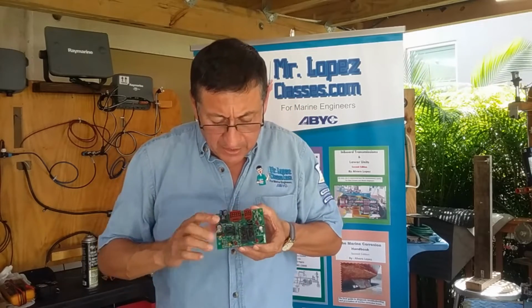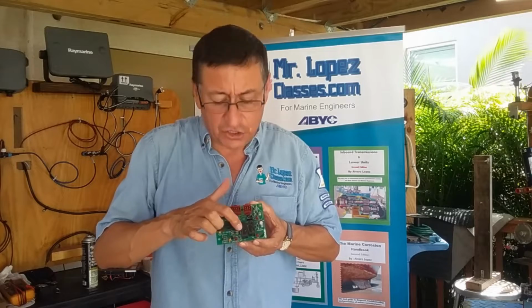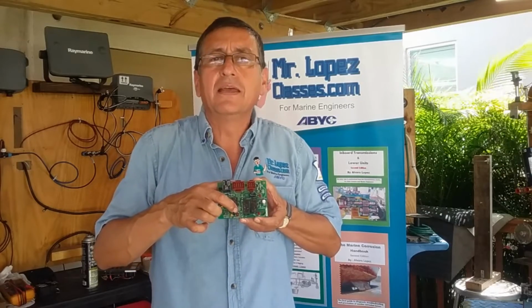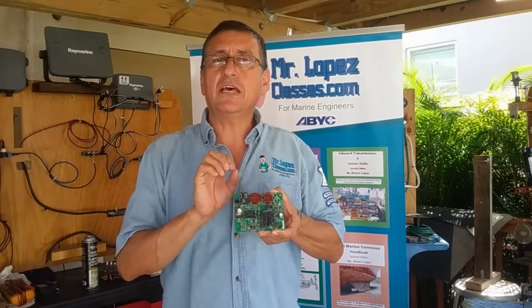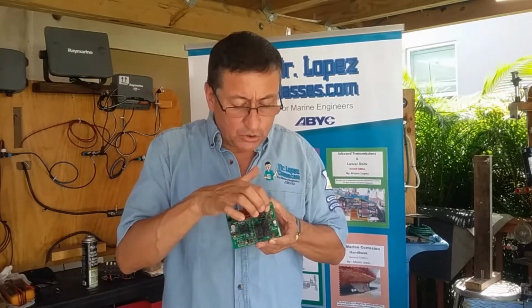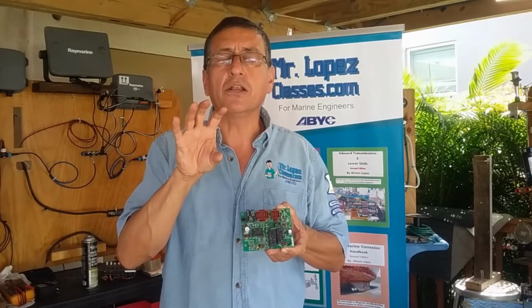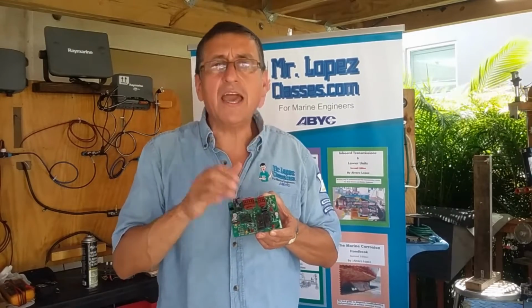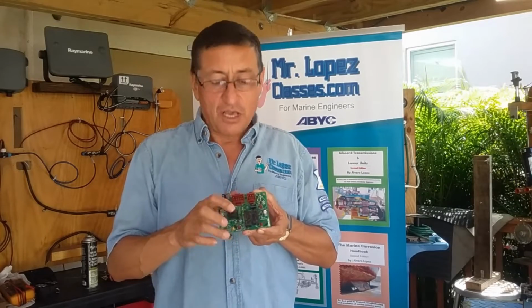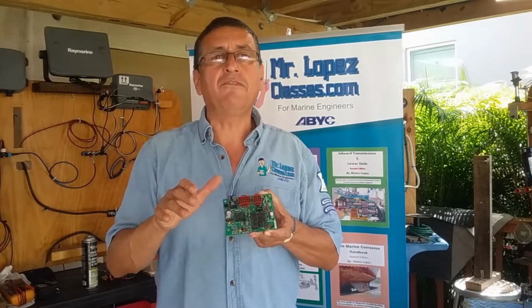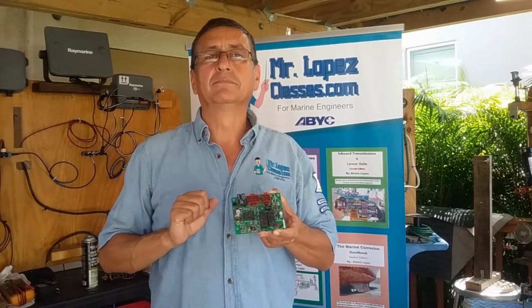If you check, in front of each relay you have an LED. Normally, if you check the manual of this engine, it says that if the engine is running, those LEDs should be solid on. If one relay is blinking, it's because probably the relay is shorted. If one LED is off, it's because that circuit is open.